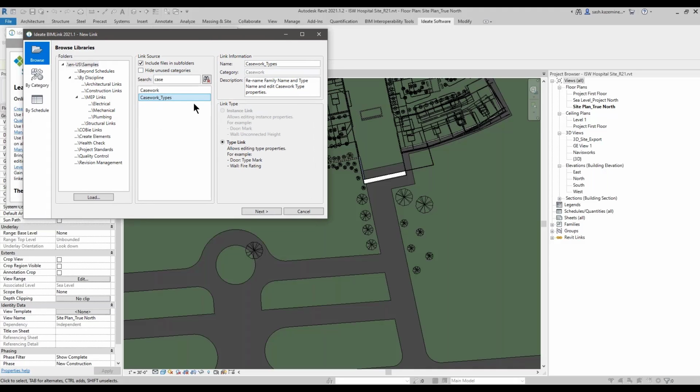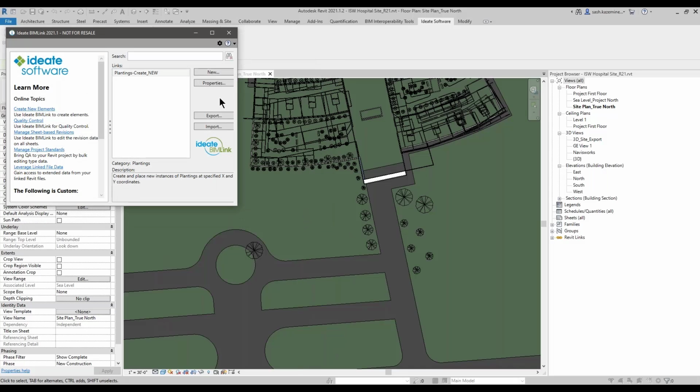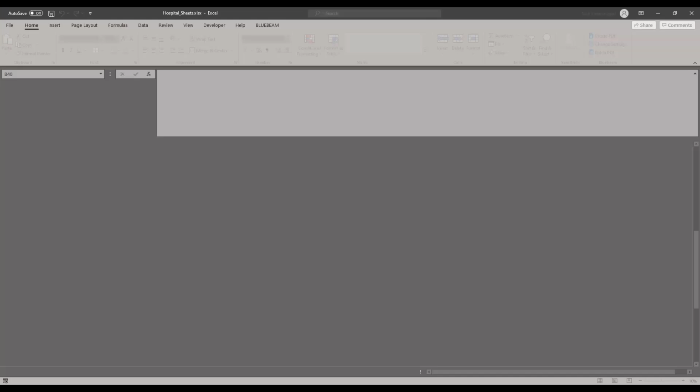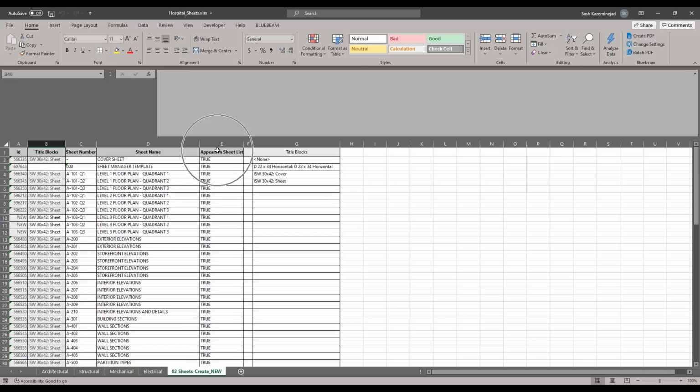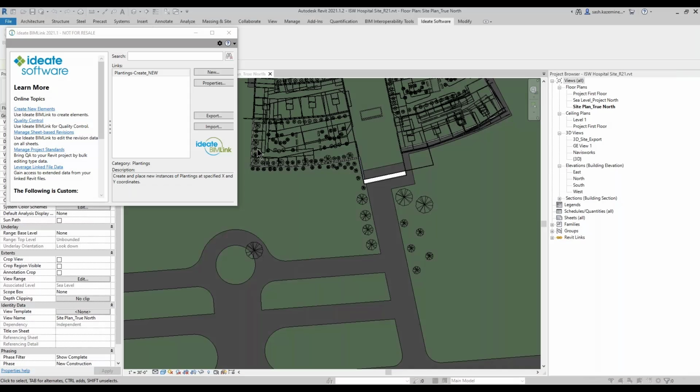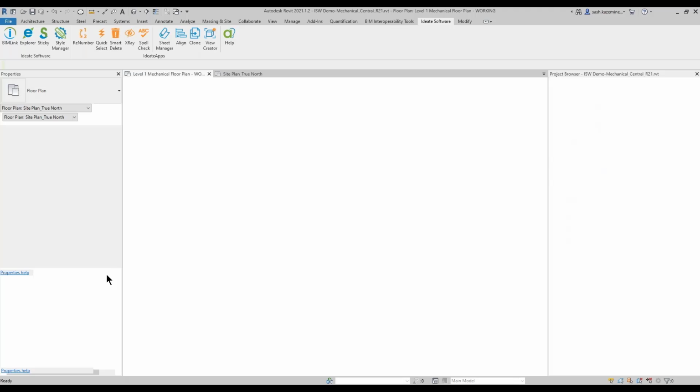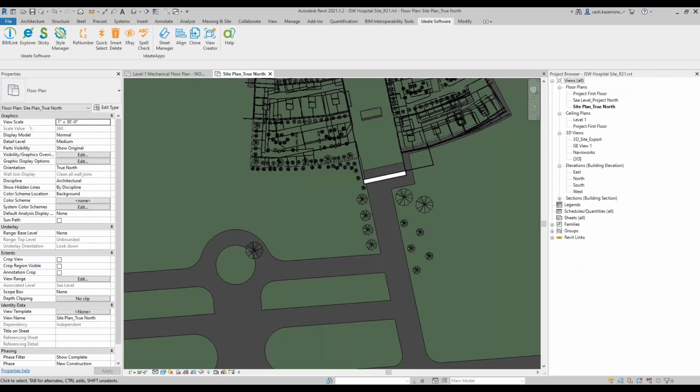Another question that came up, which I answered for the entire group, was about the sheets and the placeholder sheets, and whether they would appear in the sheet list. I said there's a property you can assign called appears in sheet list. If it's true, then it would appear, and if it's set to false, it would not appear. You're exactly right, appears in sheet list, true or false. That can control both the actual sheet and the placeholder sheet, whether they appear in the sheet list or not.